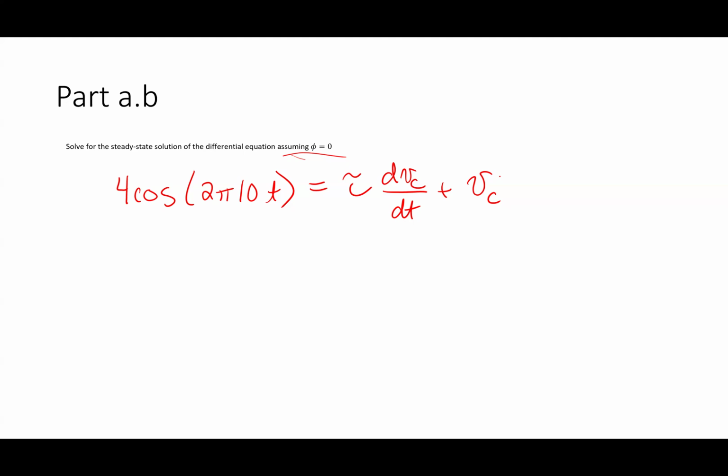So the reason why, just to catch, it's a good question, right? In physics 2, when you're learning about a capacitor, you think about the voltage on the capacitor decaying exponentially over time. It's basically because of that I equals C dV dt. It means that anytime I have a circuit with an R and a C, it's going to be a first order differential equation that comes out of KVL. So yes, it's exactly that. And so the transient response for the voltage on a capacitor is always going to be an exponential that decays. Always, right?